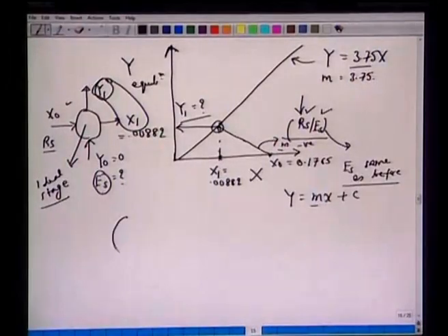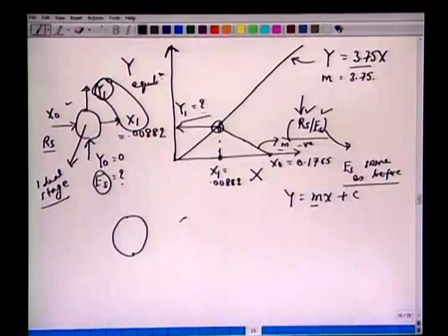So, the idea is still the same, our feed is A plus C here, and we want to reduce 95% of C in the A plus C stream by using 3 stages instead of 1 stage, and we will see how much is the difference in the solvent flow requirement. Again, one can solve graphically and one can solve by writing down the equations. So, let us draw the schematic and see how we can solve the same problem by 2 methods. Okay. So, here we have now 3 stages, 1, 2, and 3.